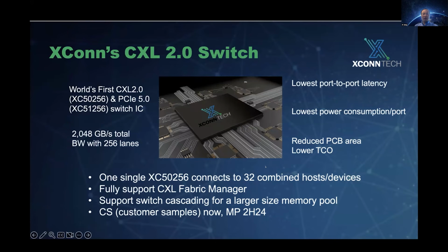The chip will be able to connect to a total of 32 ports. Each port can be by 8, but it can also be a by 16 port. And we support a CXL Fabric Manager, which is very important for CXL 2.0 memory pooling and sharing, and also more important later for the CXL 3.0, 3.1 Fabric Manager.